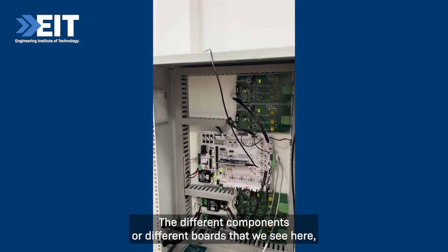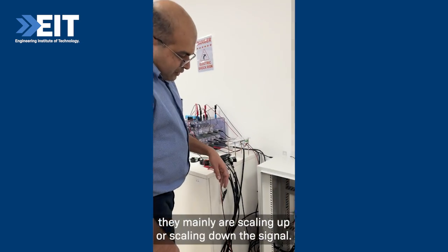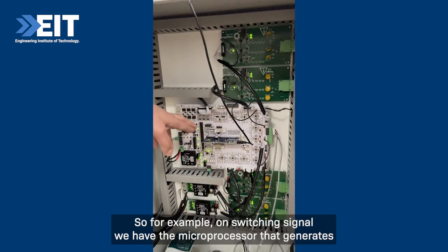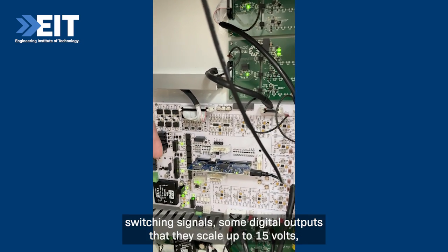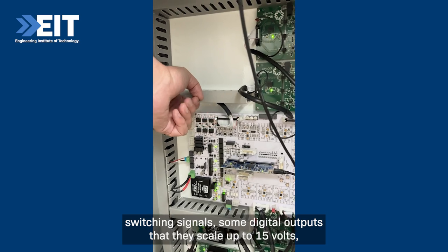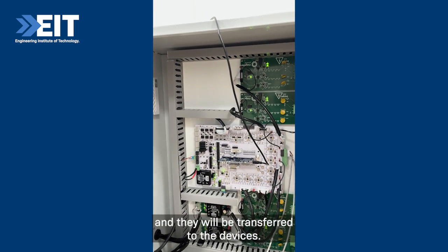The different components or boards that we see here mainly scale the signals up or down. For example, for the switching signals, the microprocessor generates some digital outputs that they scale up to 15 volts, and they are transferred to the devices.